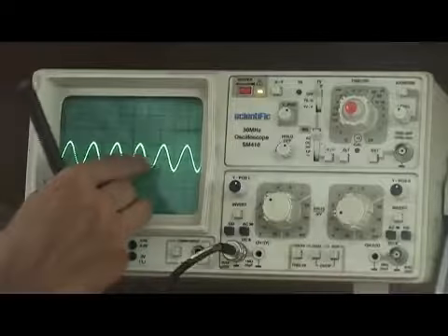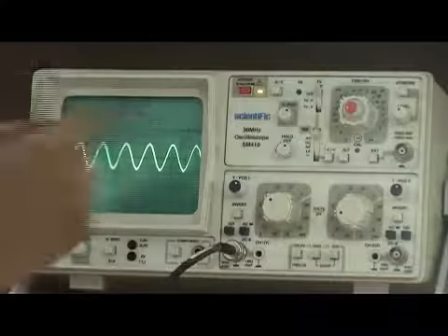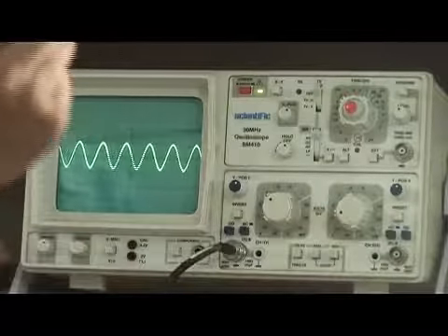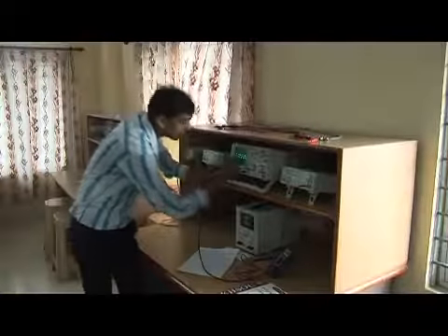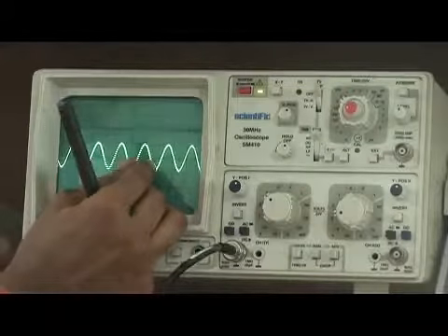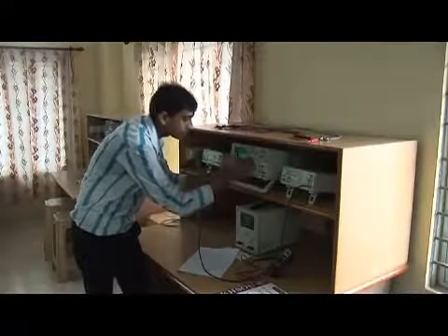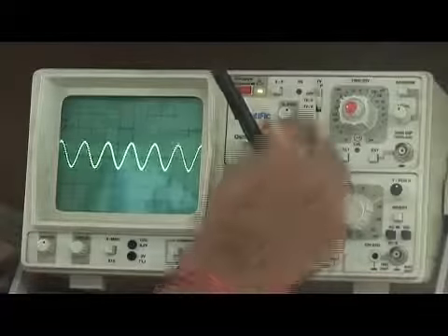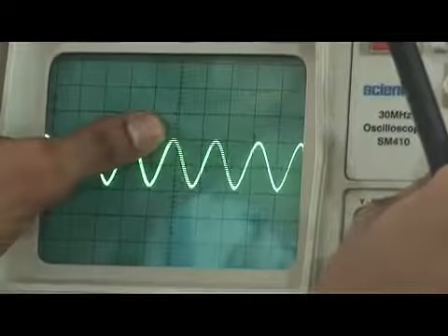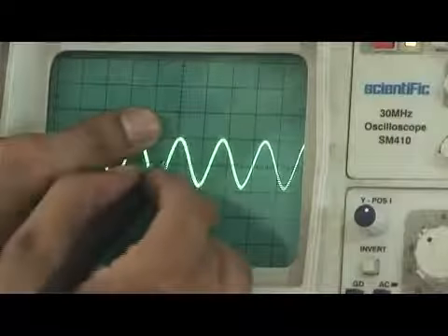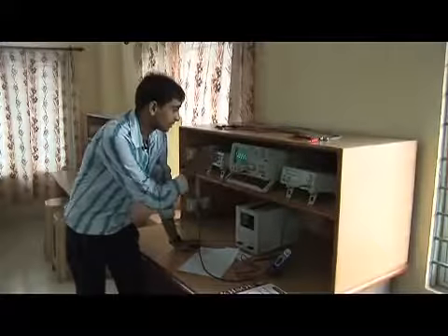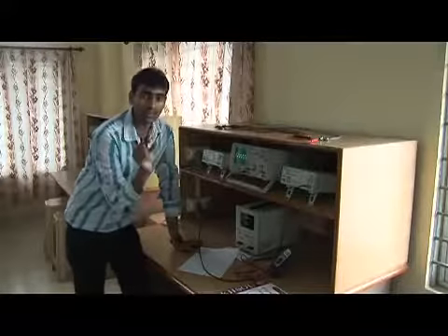From here, if it comes till here, it is repeating again from here. So it's called one complete cycle. From here to here, from here to here, wherever you take, you have to take one complete cycle. So you have to calculate how many blocks this one cycle is taking to complete its repetition. So let us calculate this. If I make it a little more stable, from here it is taking around 1.3 as the number of blocks taken by one cycle.